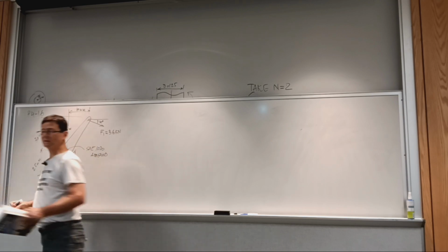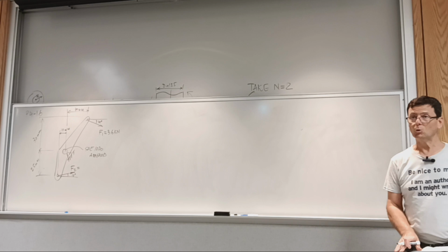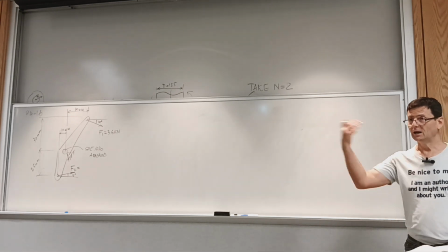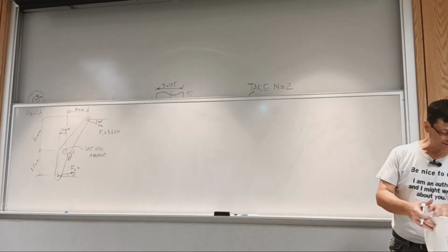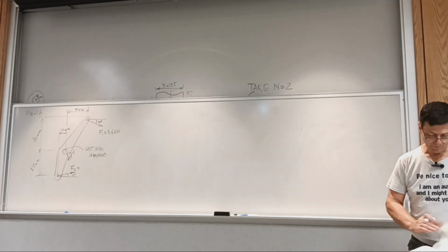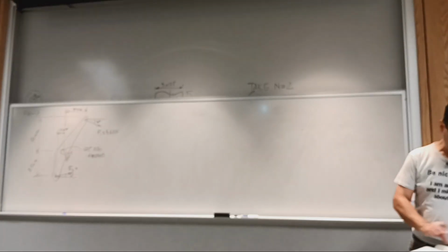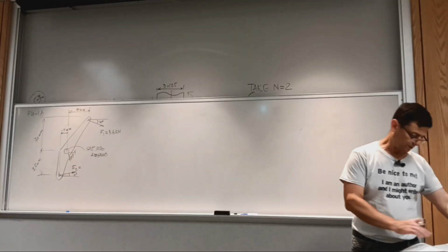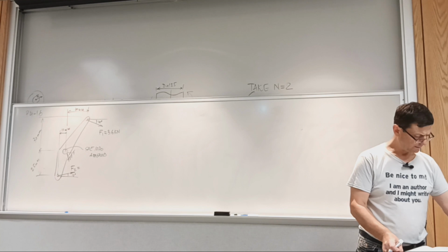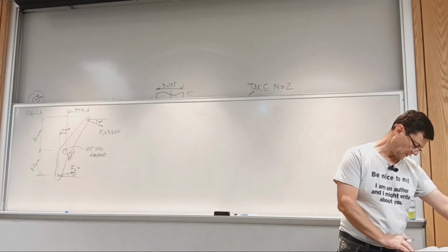Why I changed it? Because I said that beryllium copper is a brittle material, and the equations for shear are for, or the text even says if it's a brittle material, do more reading. And if we find beryllium copper now, which is together with the non-ferrous where titanium was, okay, so typical properties of stainless and non-ferrous.